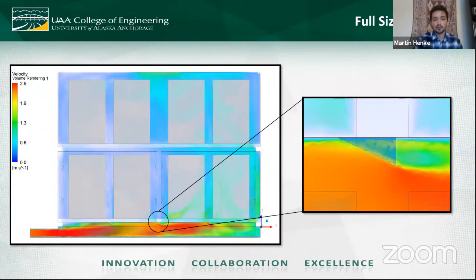The Vortex generator model shows similar behavior. However, you may notice that there are small vortices caused by the Vortex generators, which are mounted towards the back of the model. Unfortunately, I don't believe that Vortex generators in the front really received a high enough velocity bulk flow to really make a difference, but some of these towards the rear did. And I've blown up the view here. However, in general, the total behavior of the flow tends to mimic that of the default model with little variation, at least from the naked eye.